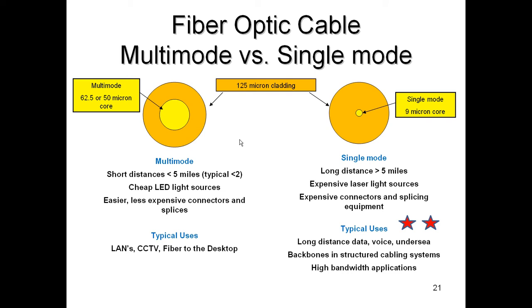And the fiber industry has been stressing for years, always pull extra fiber. If you're going to do that cable run from point A to point B, or you're going to run up the riser of a building, always pull extra fibers. You don't know when you'll want them, but you'll be real glad they're there because they're the biggest pipe. And remember, with fiber optics, it's a blinking light signal. Therefore, it is completely immune to EMI and RFI interference.